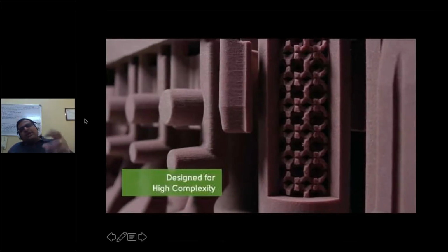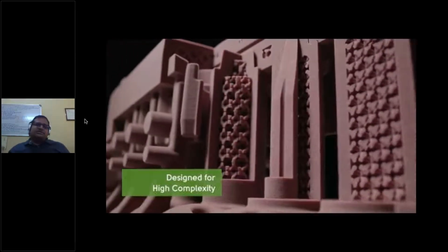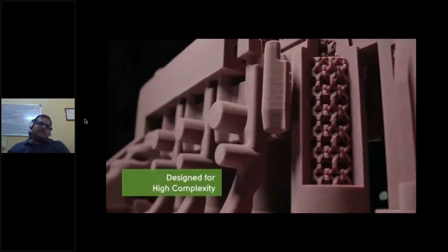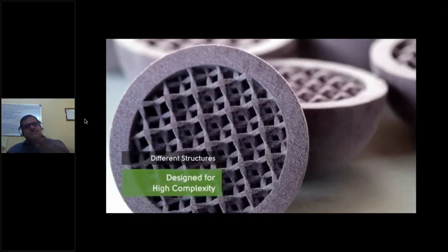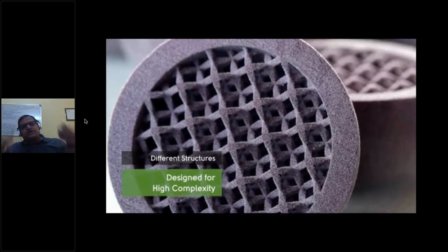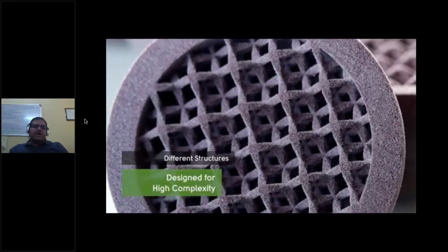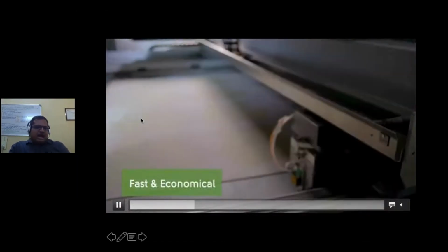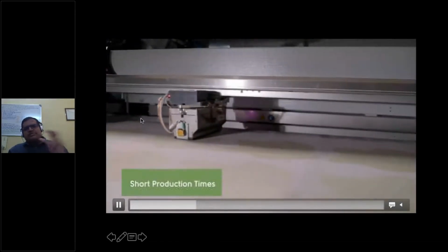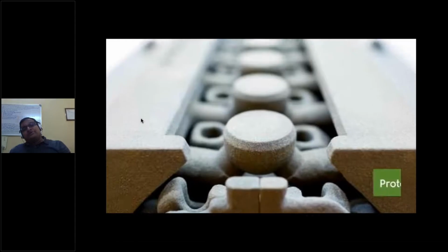So you take the raw material again. Here the powder is a sand, either silicon based or zircon based sand, and then you spread it like this, and of course use the binders to jet the binding from your nozzles. So these, which you can see, are a set of nozzles where I think it may be millions of droplets per second. You are able to jet it.